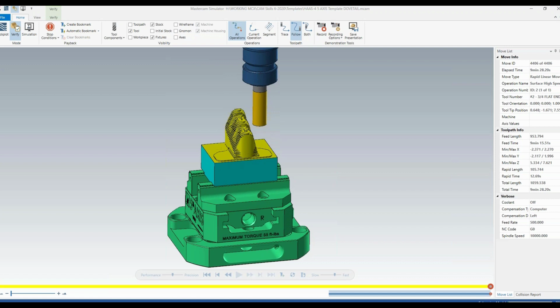Not to mention the fact that you don't get burned out doing the same 5 things over and over on every part file. Oh, I've got to create a bounding box. Oh, I've got to make stock. Oh, I've got to adjust feeds and speeds. Oh, I've got to change the stock to leave values every single time. It gets old. If I do it this way, then I'm just saving myself work down the road. So even a little bit of this can definitely save you some time.